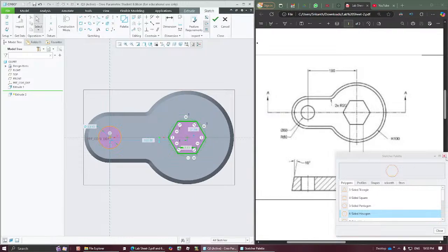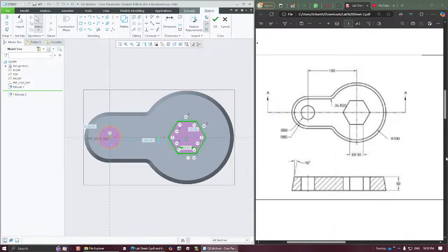Now that the palette work is over, you can close it, and here you can see 6 times we have a length of 50. Now the hexagon here has been defined in such a way that the constraints ensure that all the sides are of equal length. So we need not worry about changing all the sides at once. You just need to change this, and okay, the radius will change. Next thing, this has not got a constraint even though we had pulled it correctly.